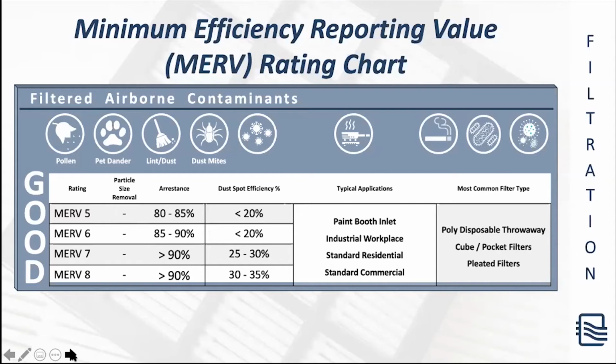Now, ASHRAE's guidance was that, well, excuse me, back up just a second here. Most buildings that we look at now will usually have air filters that range between MERV 6 to MERV 8. That is a standard MERV rating for a lot of applications. There are school districts all over the country that use filters that are rated below MERV 8. That is normal, okay? Now, anytime that we increase the MERV rating on an air filter, there are some other things that we have to think of.